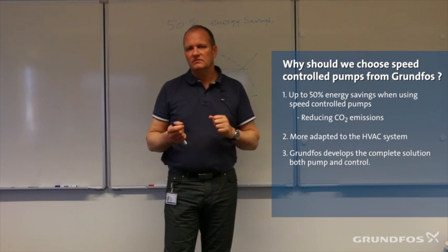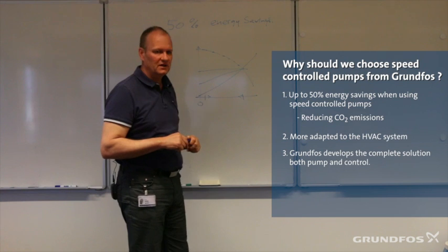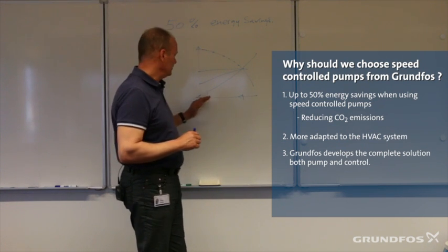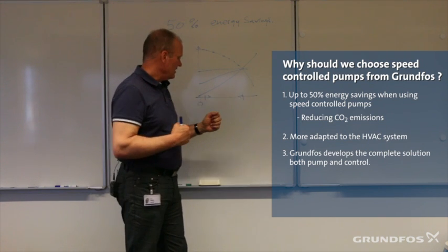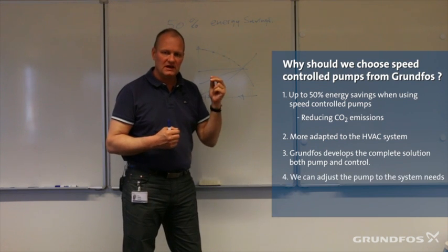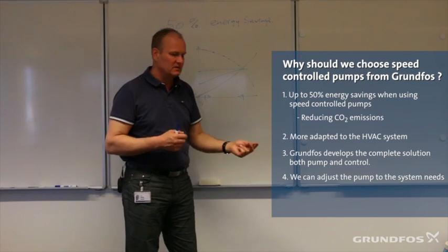But here speed control comes in handy, so to speak, because we have a certain flexibility on the QH range because we have the ability to adjust the actual duty point or the performance of the pump to what is exactly needed.